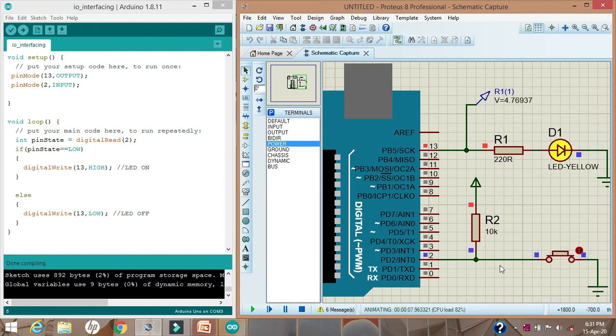Okay. Now see, this is the pull-up resistor I have used here. This is a physical resistor, an extra component we are using. You can also replace this component by a syntax in the program, which is known as pull-up programming. So let us delete this component from here and replace it with a syntax.